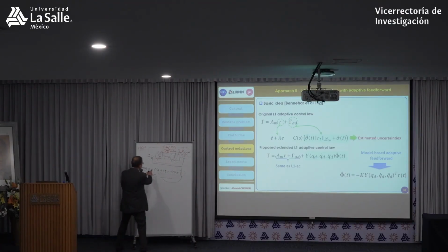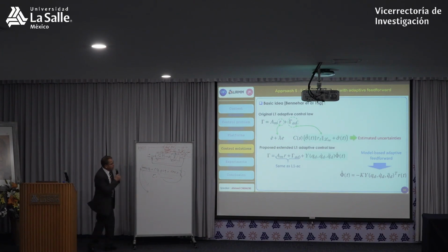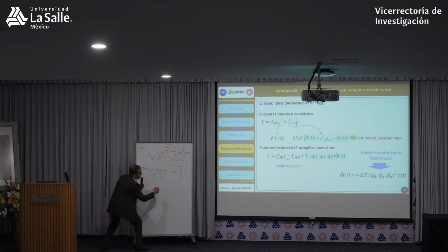It means that this equation can be written with a regressor matrix Y, depending mainly on q, q dot, and so on, multiplied by a vector, which can be theta or hat theta. So tau equals Y times theta. You write the equation like that, and the regressor matrix here is nonlinear. However, the dynamic model is written in affine form. It's a linear form because you have this matrix Y multiplied by the parameters.